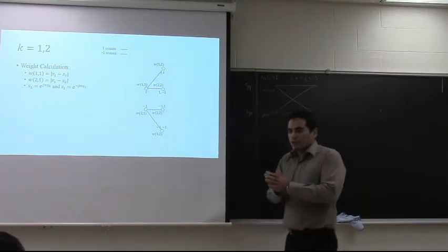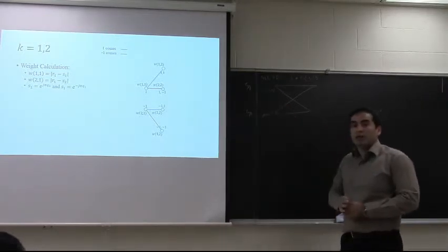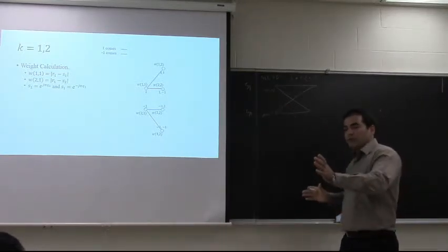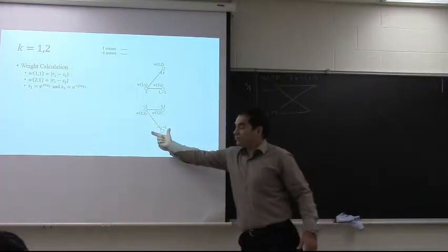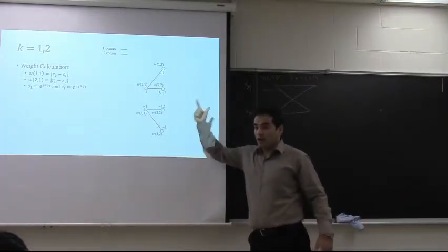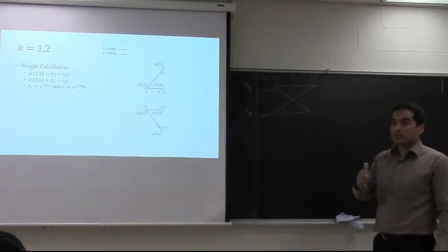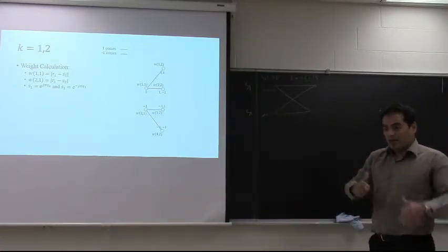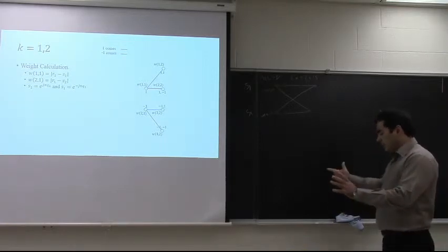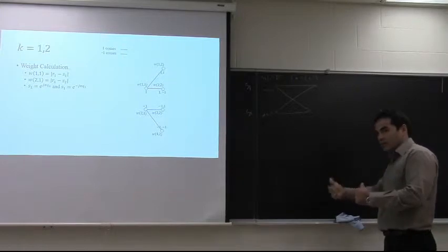We go forward, we expand the Viterbi diagram until we can distinguish what these three transmitted symbols, n, n minus 1, n minus 2, were, and also what the theta of n was. After you have the theta of n and these three, then you can distinguish where you are going if 1 comes, and where you are going if minus 1 comes.